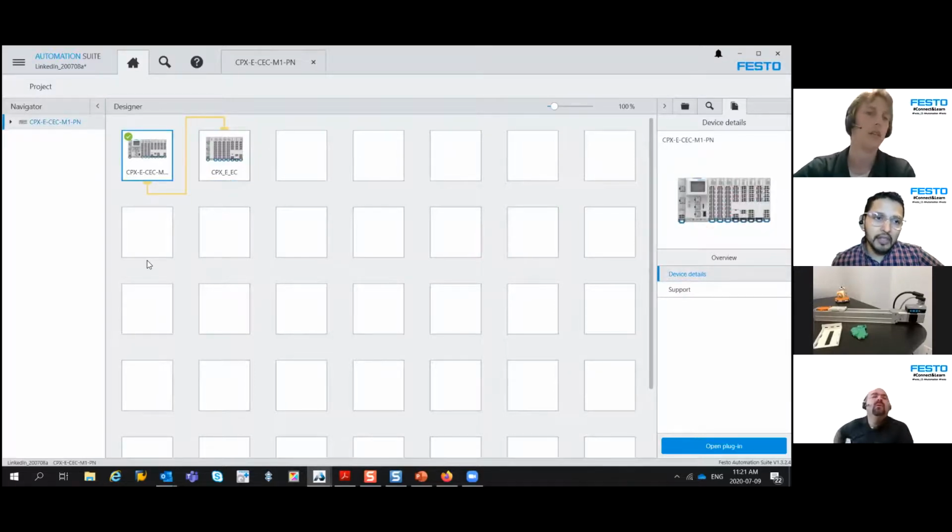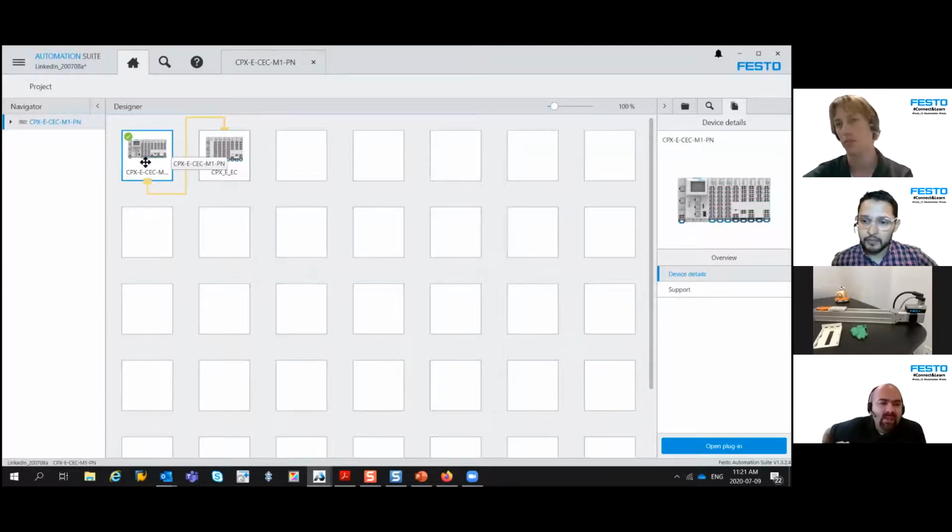On the left is the PLC, that's the controller, and the one on the right is where you have a card with IO-Link, an IO-Link master. It could be in there, but in my case, it's actually on the PLC itself. You could have it on either, or on both. Or you can have an external, remote IO-Link master on any other PLC, Beckhoff, Allen-Bradley, Siemens, connected where the machine is, and then you can run everything from that particular IO-Link master. Everything on M12 connections.